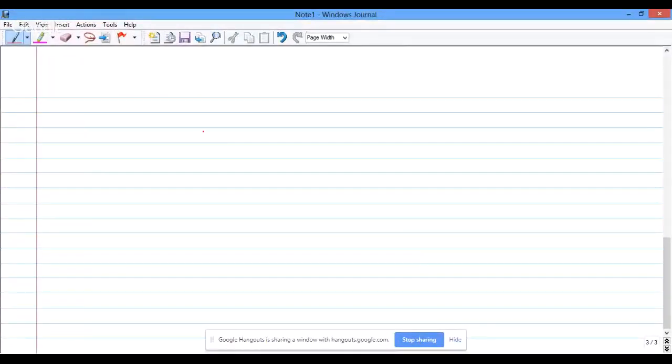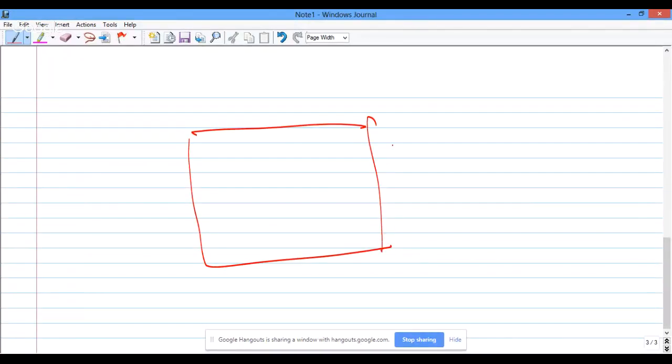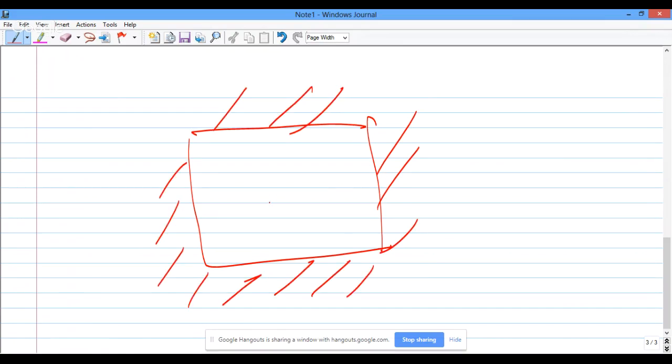Supposing this is the plot available to me, and it's all congested with buildings like this, which should not be the case. So building is there, this is my plot, and building. If I'm planning now, with a building here, I can provide a kind of courtyard. And this courtyard should go right up, and of course I have to have some amount of frontage and side setbacks left as per the bylaws.